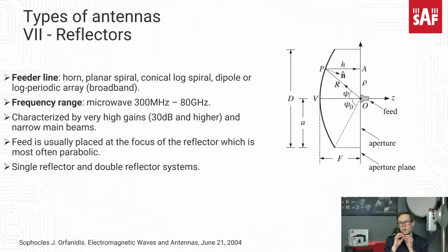As the feeder transmits in a broader angle, and different parts of a wavefront hit and bounce off from the reflector, we need to make sure that these reflections are parallel. So they are then transmitted in parallel along the axis of the reflector for better directivity.